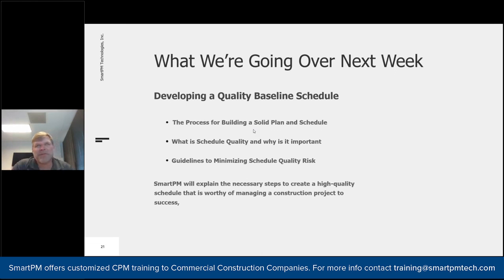It needs to be proven it was critical because that is the only path that can delay a job, as we discussed, which comes with a lot of challenges because a lot of schedules are arguable at best and the critical paths are arguable at best. But once you can prove that it was a critical path delay and it was not anything that you caused as a contractor, then you are allowed an extension of time and it is compensable.